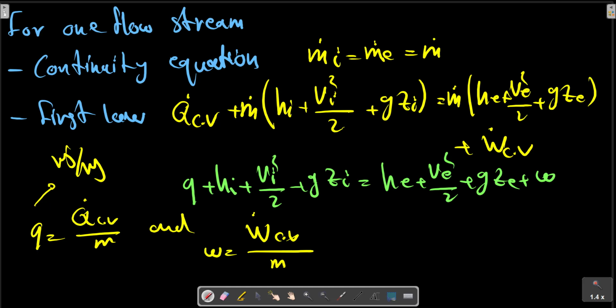The steady-state process is often used in the analysis of reciprocating machines, such as the reciprocating compressor or engines. In this case, the state of flow, which may actually be pulsating, is considered to be an average rate of flow for an integral number of cycles.